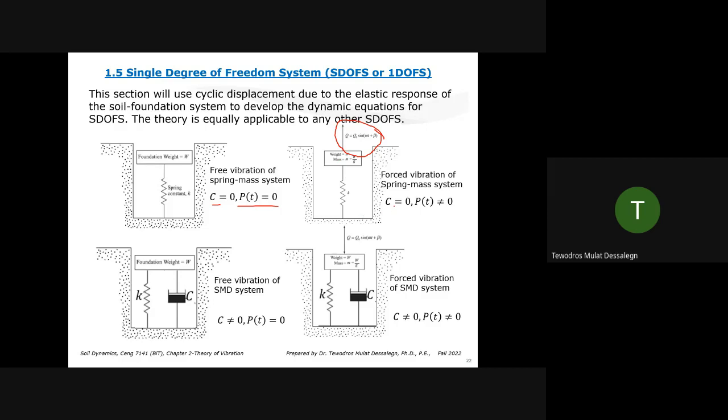When we say there is damping and there is no damping, it's how we simplified it. By nature, there is always damping. But the way we approach these problems is from the simple one to the more realistic one. So we'll first see just a spring mass system with no force. Then we'll look at it with force, with no damping. Then a free vibration with stiffness and damping model, how the equations are, how the vibration characteristic is. Then finally, we will look at the more complex case, where we have everything.